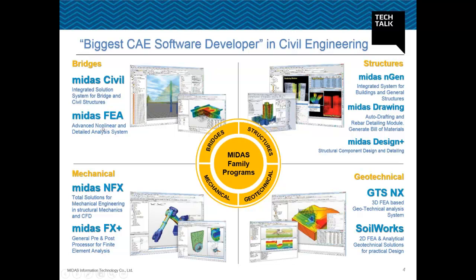Then there is MIDAS FEA, which is for advanced non-linear analysis for detailed and complex structural problems such as en-bloc analysis for a PSC composite girder, connection between concrete and steel at the pier or abutment supports, and so on.